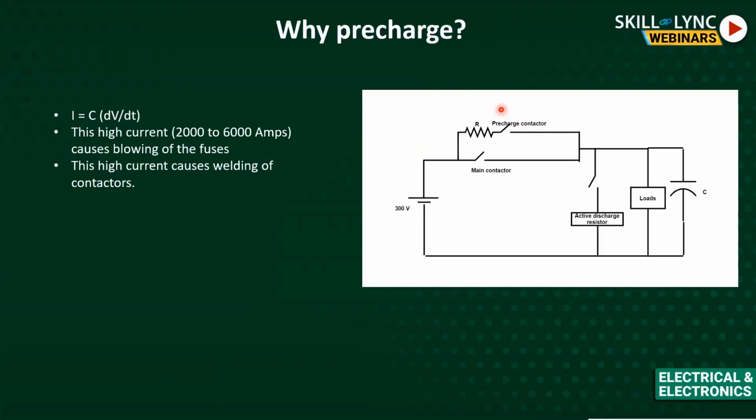If I connect, let's assume this pre-charge contactor is not there, and I'm directly connecting this voltage source to the loads, then the current will be very high.